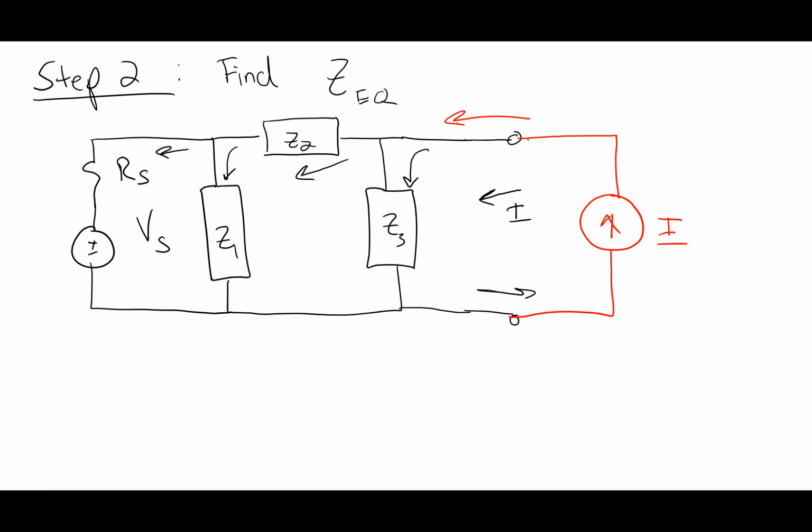So if I have a voltage source and I turn it off, what does that mean? Well, let's think about it. Turning it off makes its voltage equal to 0. You're just thinking 2 steps ahead if you start saying it's a short. A voltage source is a fixed voltage, and turning it off means its voltage goes to 0. If its voltage goes to 0, it is now a what? A short. It's a wire, right?